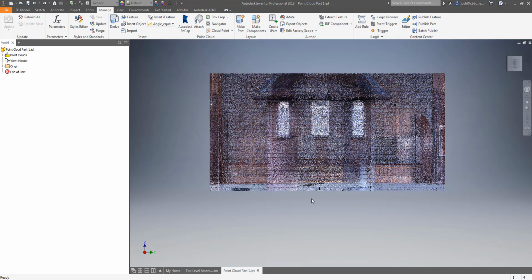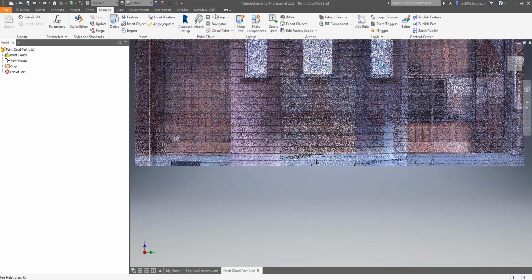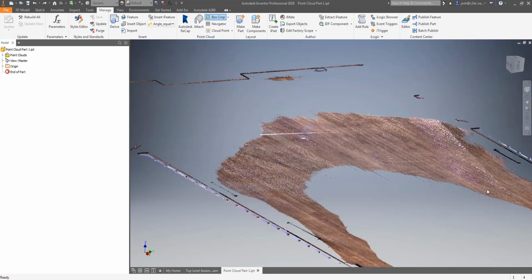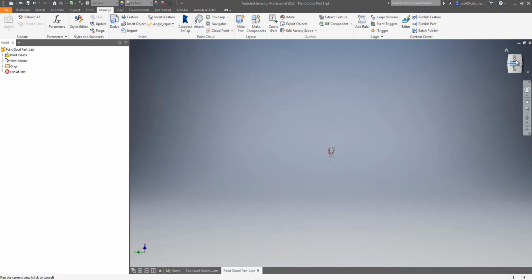Often, a super thin slice through the point cloud is the best approach. You should take this slice at a level you intend on tying your 3D model into the point cloud as opposed to the level that your sketch is on for the best results. I'll get back to this later, but for now, we will assume that this suits us best to take a slice through the cloud at about the floor level so we can trace the walls.